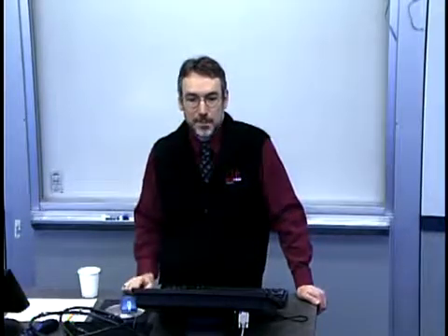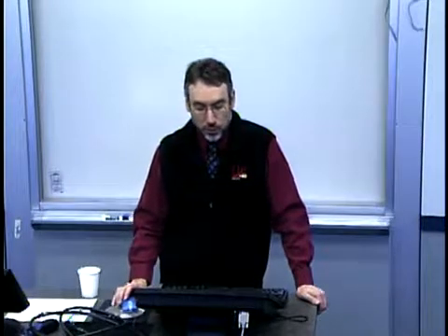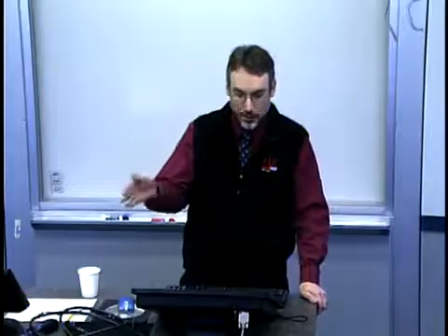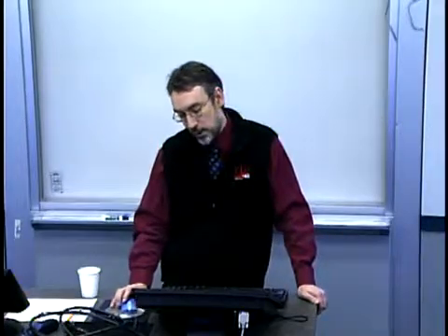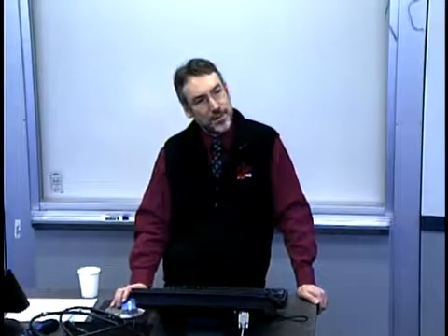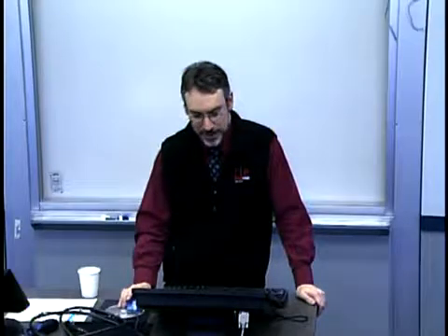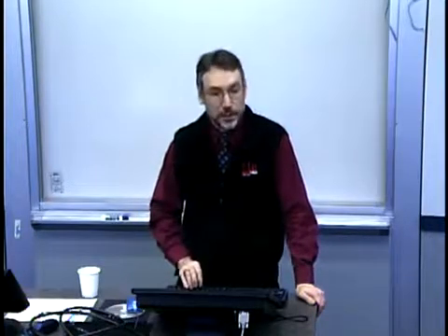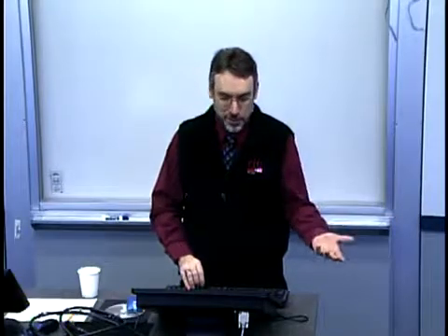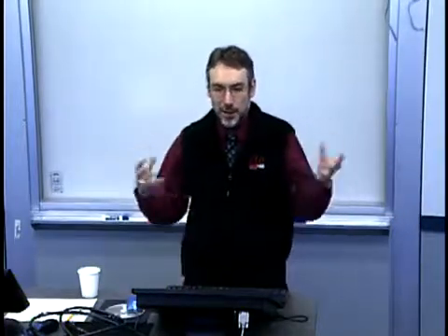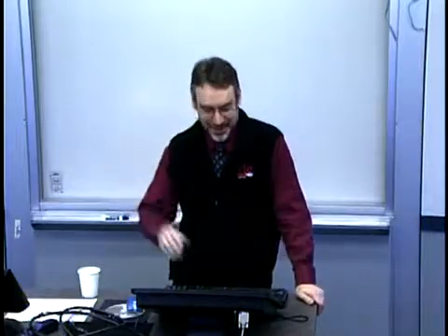Other ideas? Maybe there's a variation of time across the... there's temperature variation over time. Right. So run number is a stand-in for time, and these are occurring over time. So your point here is, sure. Right. So it may not be equipment state directly, it may also be the rest of the facility environment or the line, and over time, who knows? Maybe this thing starts heating up, or the work pieces that are coming in have a different temperature. It's quite possible that there could be some other long-term state change.